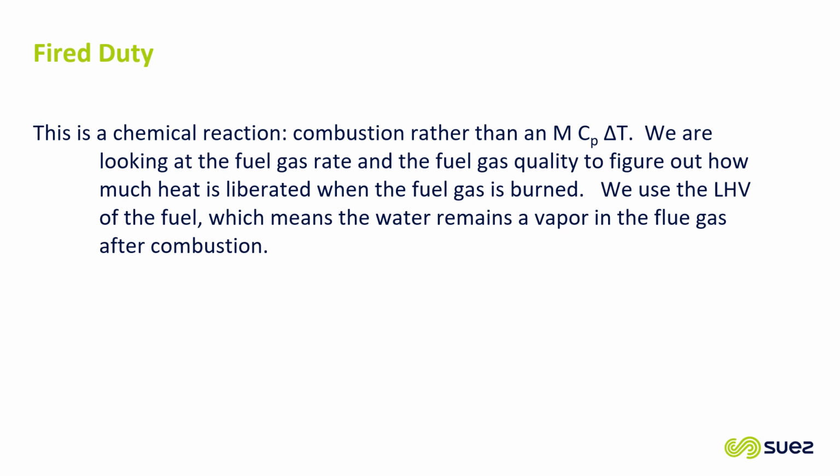If you have a super efficient natural gas heater at home, that will use a larger heat exchanger for the flue gas, and it will allow the water that's in the flue gas to condense so that you're not exhausting that steam, but instead you are capturing that latent heat of the water. That's not practical in a refinery, so in all cases we use the LHV, and that's what would be reported here.